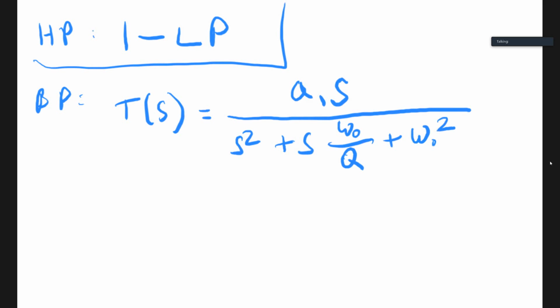And remember that while the zeros give us the behavior, the poles give us the selectivity, and therefore they give us the frequencies of the bandpass. Again, applying the quadratic equation to the denominator, we come up with these frequencies, at the system level again.